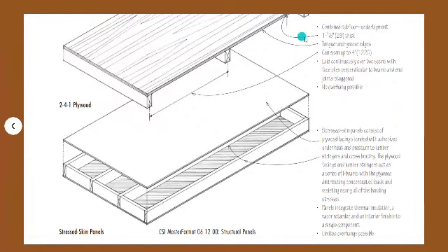At the top, this is the combined subfloor underlayment with a thickness of 29 mm, and here this is the tongue and groove edges, and here, like the distance between the two wood planks, this can span up to 4 inches. And now at the top here, this is the stressed skin panel that consists of plywood facing bonded with adhesives under heat and pressure to lumber stringers. And just at the bottom, this is the stringers and cross bracing.